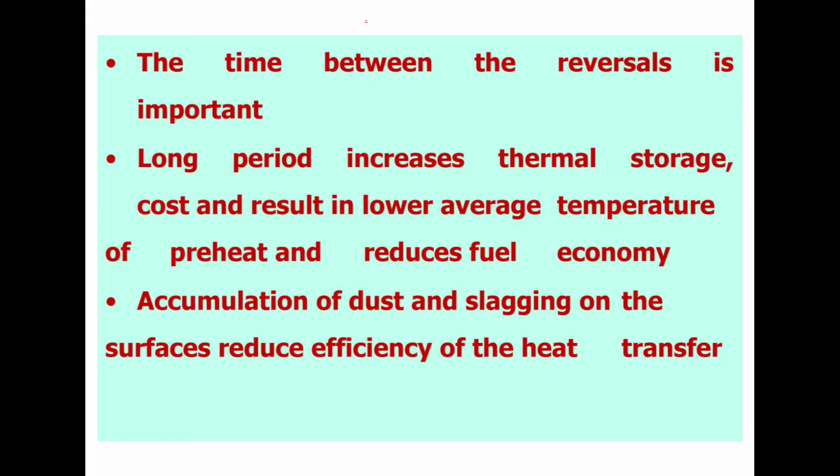The time between reversals is important. A long period increases thermal storage costs and results in a lower average preheat temperature and reduced fuel economy. Accumulation of dust and slagging on the surfaces reduces the efficiency of heat transfer.